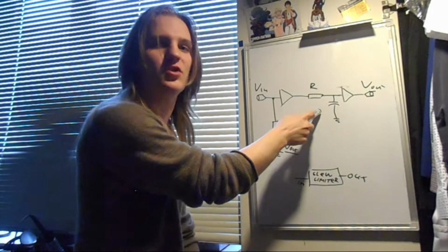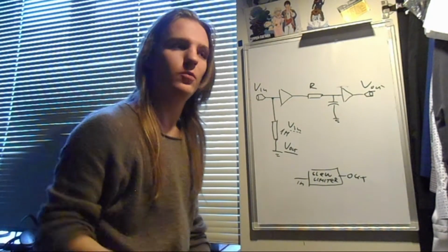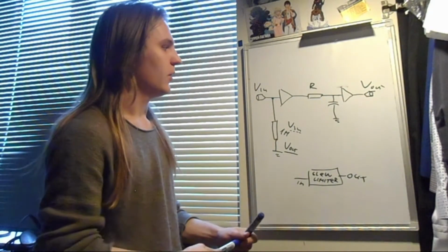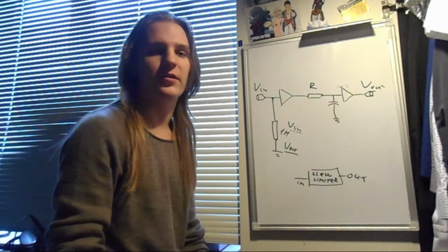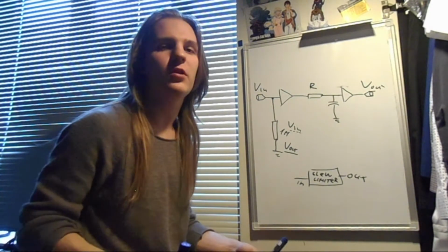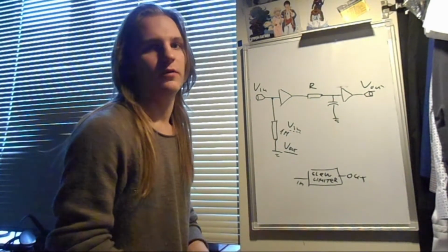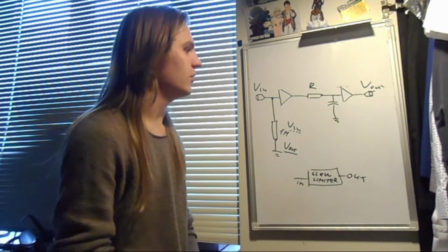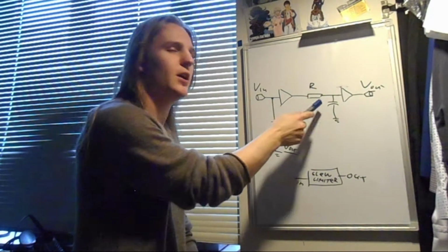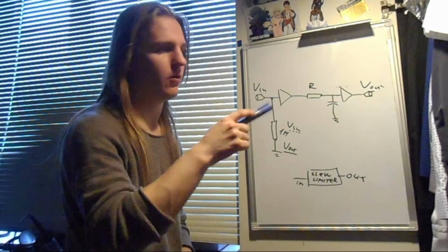This capacitor starts charging slower and slower, thus making the charging slope longer and longer. The input is not necessarily a square wave, it can be anything you want to apply here, like some sequencer, even a wave, if you have a little capacitor right here, like 5 nanofarads or something. So it will simply determine how quick the voltage goes from high point to the lower point, or vice versa.